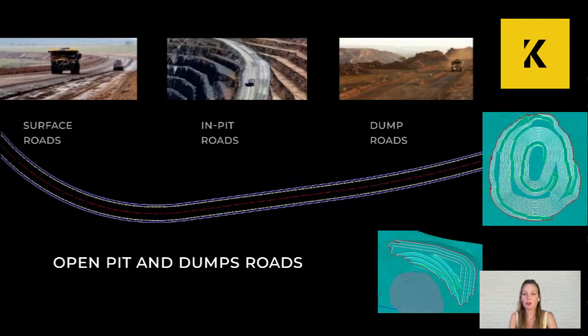Lastly, let's talk about roads on dumps. Since dumps can be made of softer rock, the road base and surrounding area need to be reinforced with sturdy materials to support heavy equipment. These roads should be wide enough for the largest transport vehicles and comfortable to travel on. To access different dump tiers, we place horizontal inserts on the slope parts of these roads.